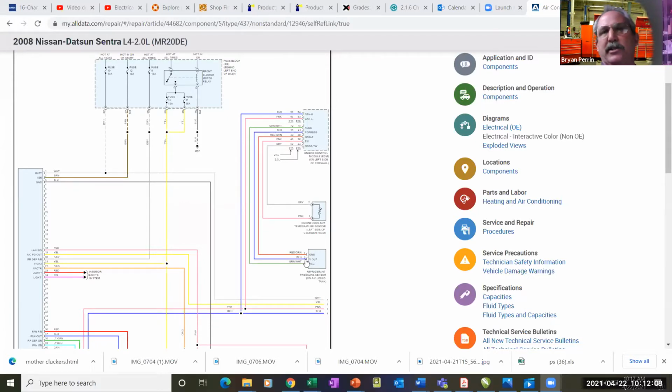Okay, now I'll ask the intelligent power distribution module, can you have AC to turn on the AC? Now it's its job to manually turn the relay on. And since it's doing it during the self-test, that tells me the wiring in the intelligent power distribution module and the network to the intelligent power distribution module are working. Otherwise, the control to turn it on wouldn't have worked.